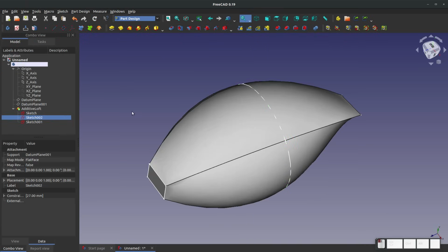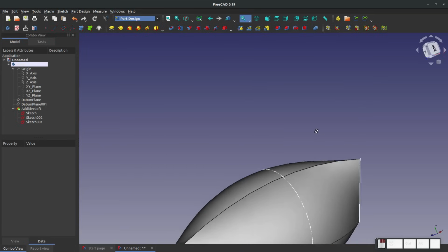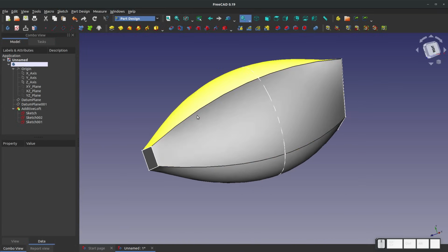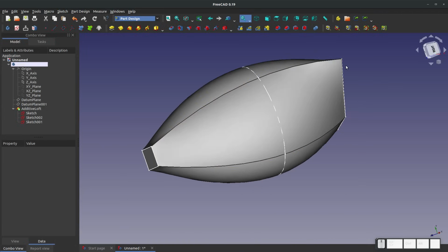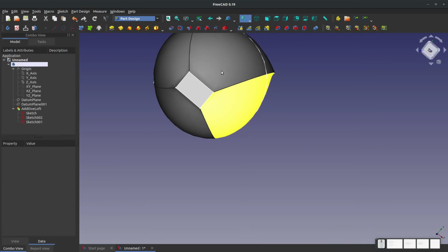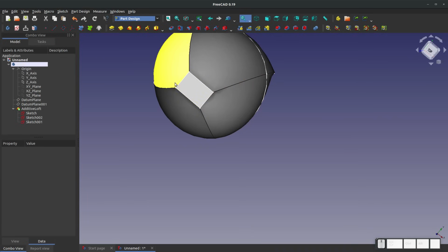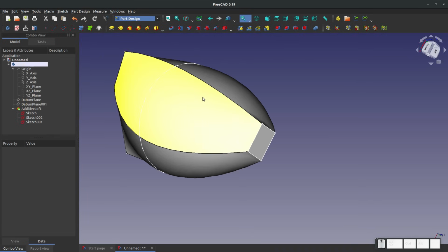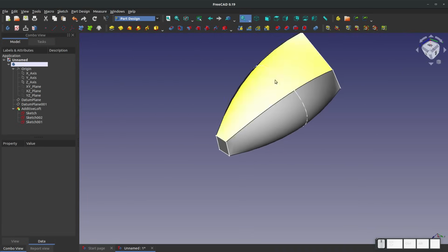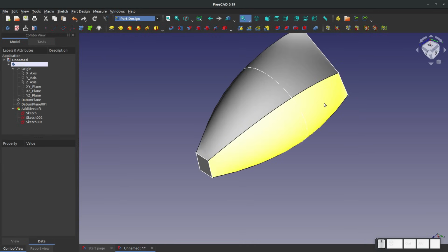So let's close that, and you can immediately see that as compared to last time, we have only 4 lines because we only have 4 vertexes on our start and end constraints. So it's a much better loft to be able to loft to the same number of elements. Hopefully you see the difference that made.